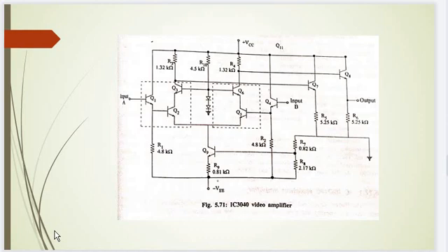It can accept a single-ended or a balanced input signal. The transistor Q9 provides the current sink biasing for the differential stage, and the resistors R3 and R4 act as a load resistor for the differential stage. The diodes D1 and D2 with resistor R10 provide the DC biasing voltage for transistors Q2, Q3, Q5 and Q6. The bias voltage for current sink transistor Q9 is applied by the voltage divider using the resistors R7 and R8. By using the bias voltage and resistor R9, the quiescent current of Q9 is obtained.